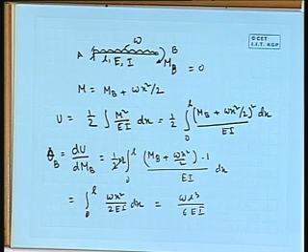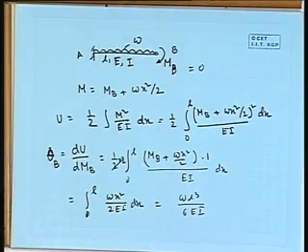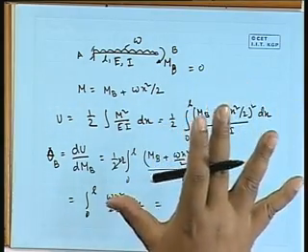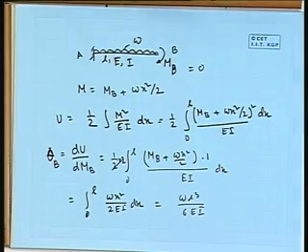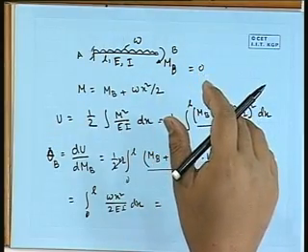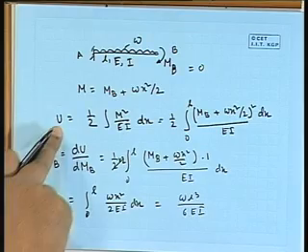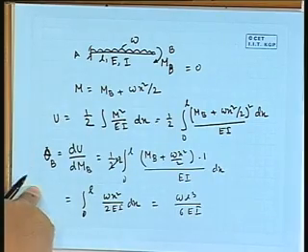Right. So with that, at least we came to that level that we have to write the expression of bending moment in terms of force or moment, then put in that energy expression, then take the derivative. At that level, we can really put the value of the load and perform the integration. Finally, we will get the deflections.